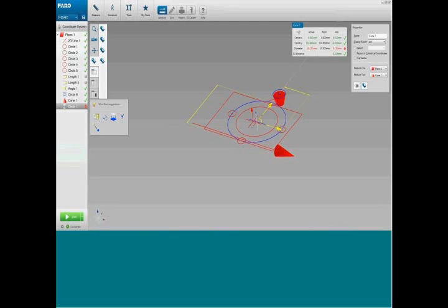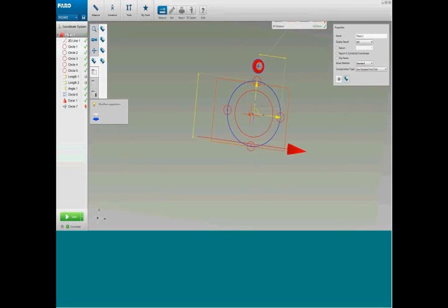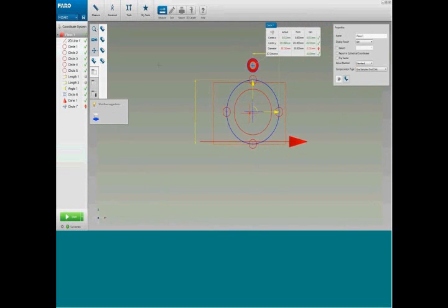So when using GD&T, I need to tag the relevant features as datum, using letters which are usually detailed within an engineering drawing or a blueprint. In this case, plane 1 is datum A. So I first click it in the feature tree. I then look in the properties, and I can tag datum, and then I can choose the relevant datum letter. In this case, plane A. You will see now in the feature tree, the plane is now tagged as datum A.